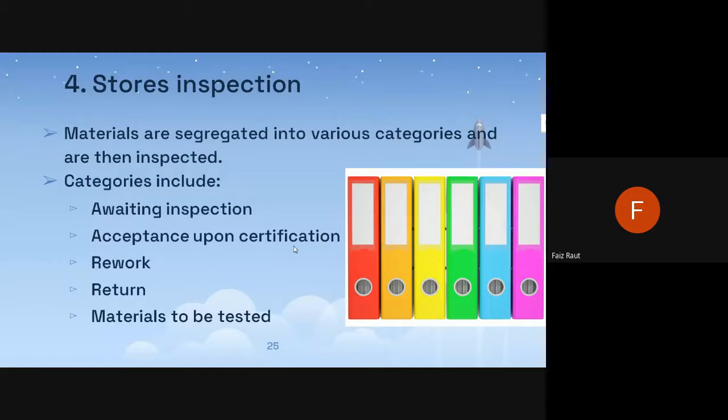Okay, inspecting our products. There are four kinds of inspection. First is pre-dispatch, just before we send the materials, while we are getting ready; one inspection will be done at that time. Final inspection is mostly done for the semi-finished goods when they are being fitted into the final product. The pre-dispatch inspection is mostly done at the supplier's location. The final inspection will be done at the owner's location or a third party where they are fitted.